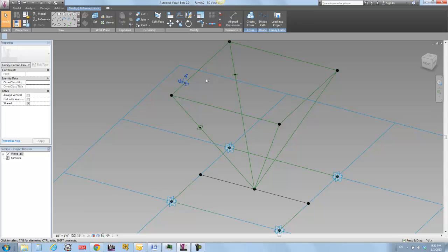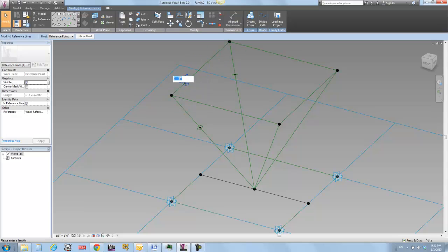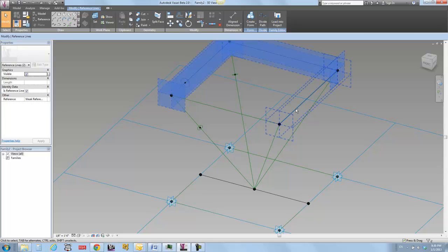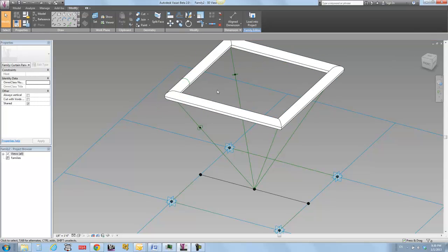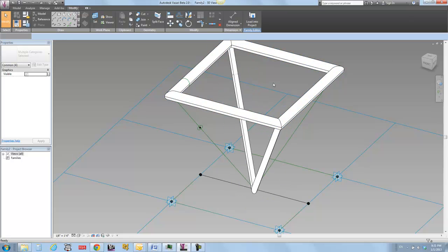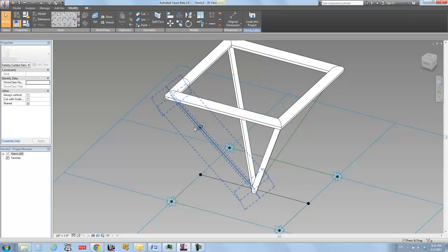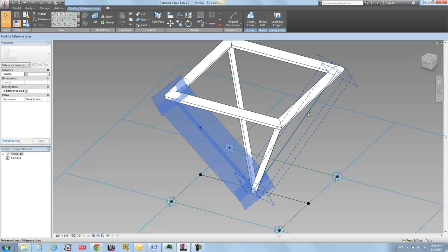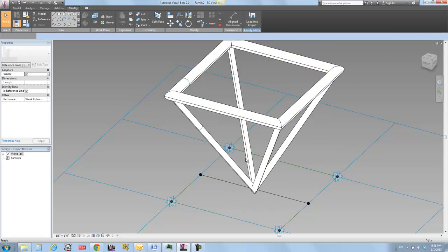So it's a big beefy strut, but let's make this one even beefier up here on top. Let's make that 5 inches. And so now I can just start making my sort of realer geometry. 1, 2, 3, 4, 5, and I create a form. So now I've got a nice top bar, and I can select these guys, and I'm going to make one sweep that goes down and back up. That's not how you'd really build it, but we're just roughing this thing out right now. And I'm going to get this guy too, and I'm going to create form from that.